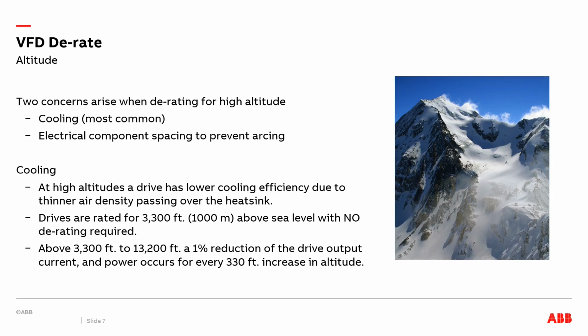So let's get into altitude. There are 2 main concerns when we're talking about derating for high altitude. The first one is cooling, which is our most common, and the other concern is electrical component spacing, which is there to prevent arcing on internal components.